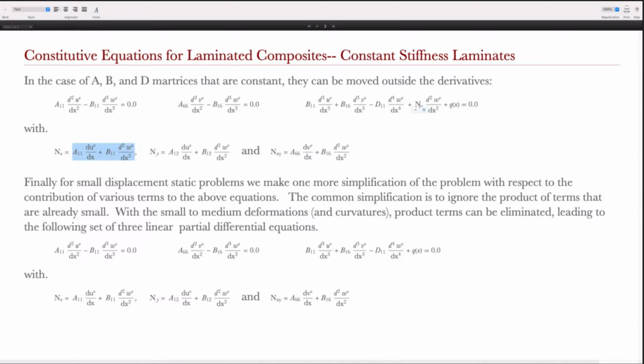That means finding the buckling load at which this plate is in equilibrium, and if I perturb it, it comes back into its original configuration. But this is a problem where Nx and W are really coupled. Nx is applied, the plate is curving. This buckling problem cannot be solved by completely ignoring this Nx term.